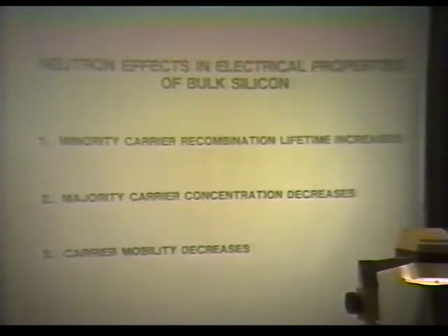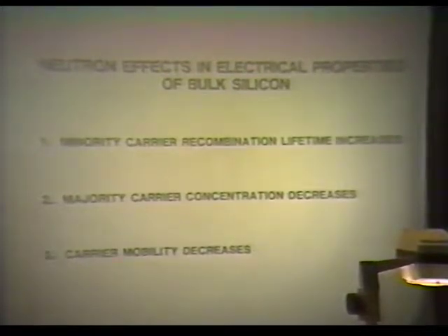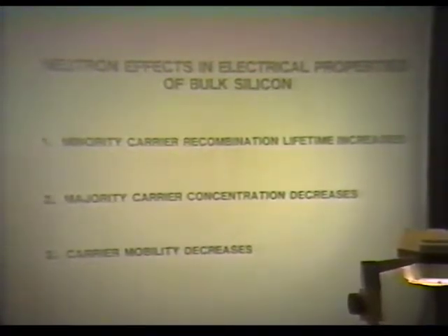And so as you decrease the efficiency of transporting these carriers across the base, you also decrease the efficiency of your transistor operation, and the gain goes down. The HFE gain, whatever you call it. So you're just shooting yourself in the foot by creating defects in there that act as traps. And so the lifetime of your carrier going across there is decreased a great deal because it's got lots of traps to fall into. It doesn't live nearly as long, doesn't go nearly as far, however you want to look at that.